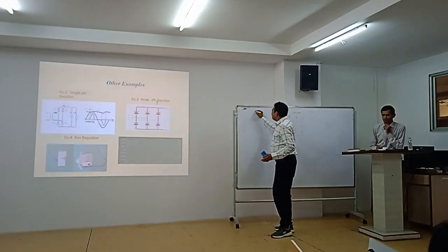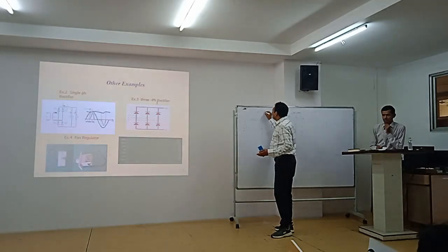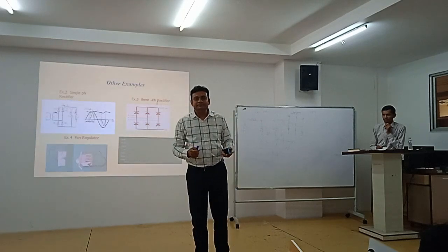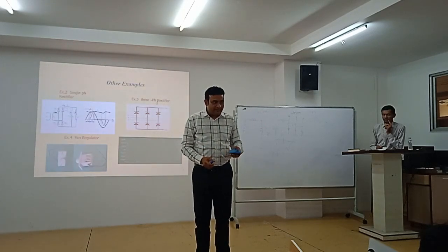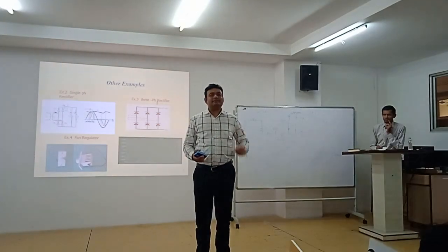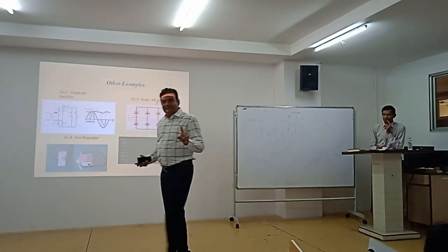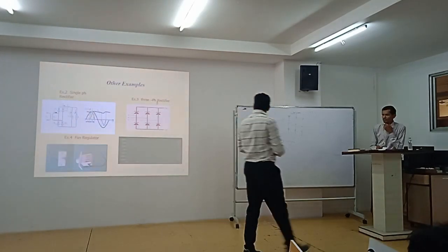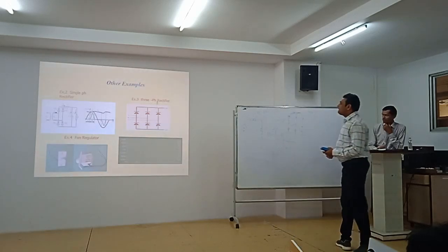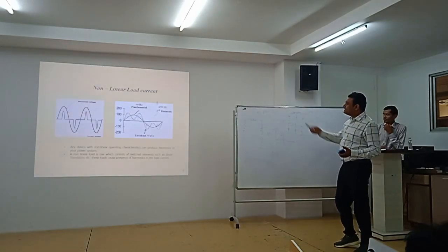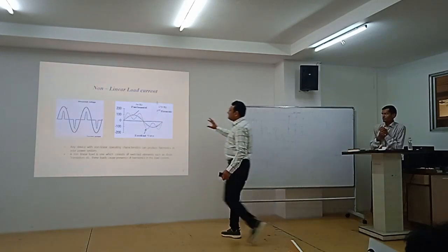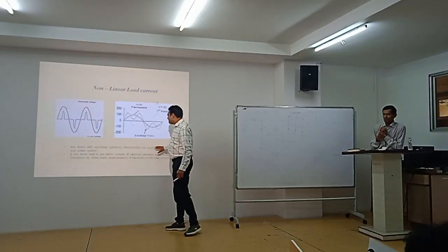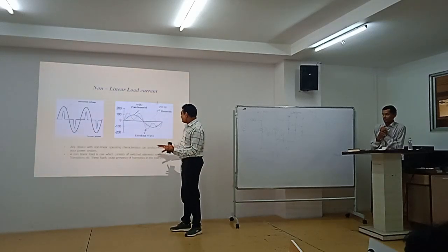So the 11 kV and 33 kV that come in a transmission line, which voltage are they? Line to line. RMS. Line to line RMS. So speak like that. It is line to line RMS voltage. Right? Okay. Next. So these are non-linear loads. Few patterns are shown. Single phase current. Any devices operating in non-linear mode, they are non-linear.